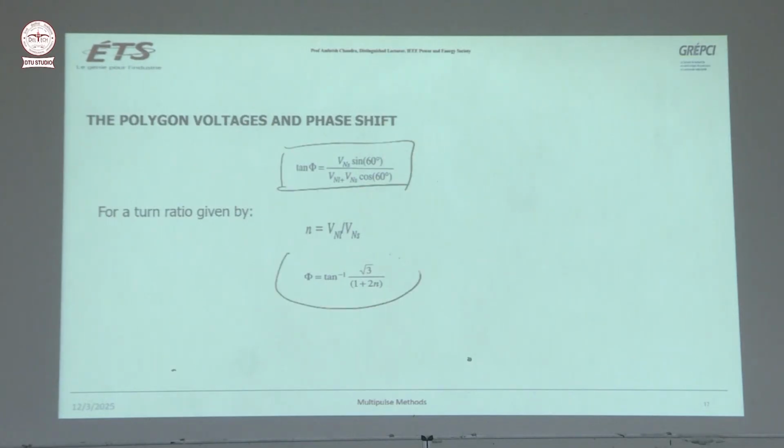The objective is to find the angle phi. So how you will adjust the angle phi? That depends on the requirement, what kind of load is there, what harmonics are generated. So depending on that, you can do the calculation, which phase difference between the transformers will be helpful to cancel certain harmonics. Accordingly, you calculate phi, and phi you can adjust by the transformation ratio.